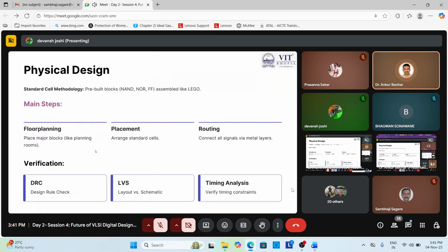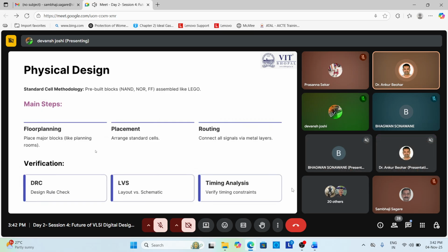Now we have DRC. Under verification, DRC plays an important role. It is used in electronic design for integrated circuits, and also for PCB boards, to verify that a design meets the manufacturing and performance constraints. It ensures the design will not result in defects or failure by checking parameters such as trace width, clearances, and spacing against a set of predefined rules.